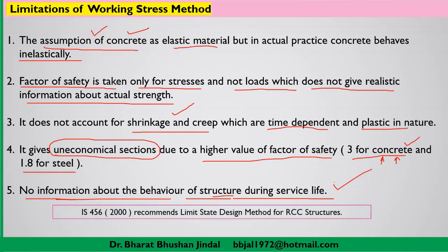So IS 456 now recommends the limit state design method for RCC structures. You may use the working stress method in the design, but then you have to face all these limitations and you have to compromise on some of the properties of the structure as well as the economy.